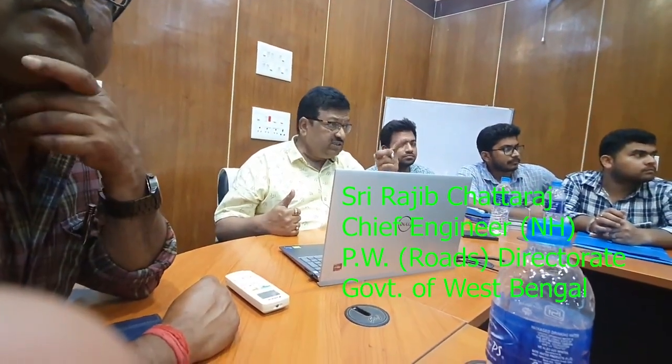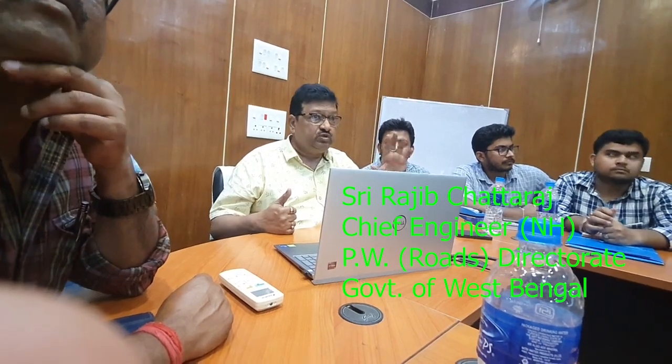And now IIT Kharagpur has submitted the report. It was an NHAI sponsored project. The report has been submitted, and probably an IRC code is also going to be published about this. It has the potential to replace the conventional PQC. In conventional PQC, we go with 300 millimeter odd thickness. Here it will be just half. So how much material will be saved, you can just imagine.